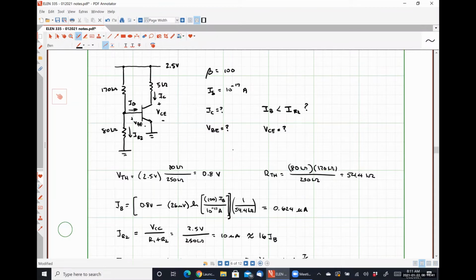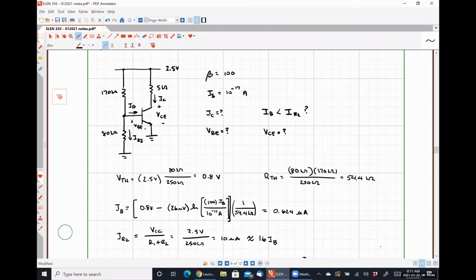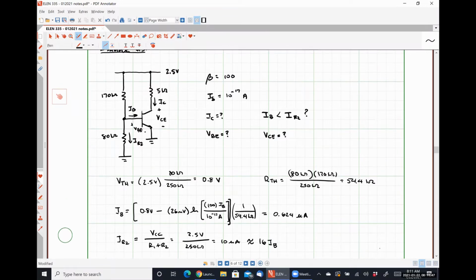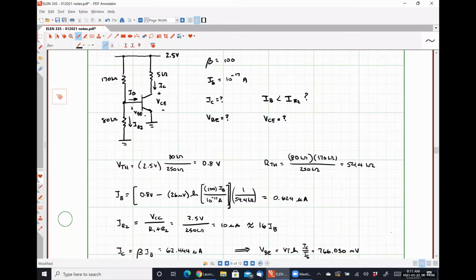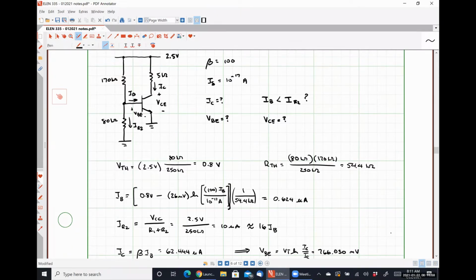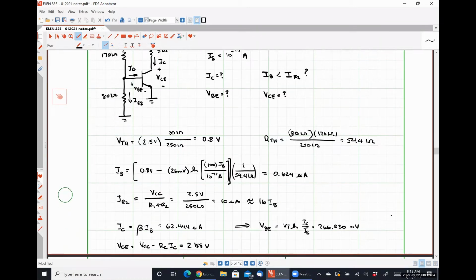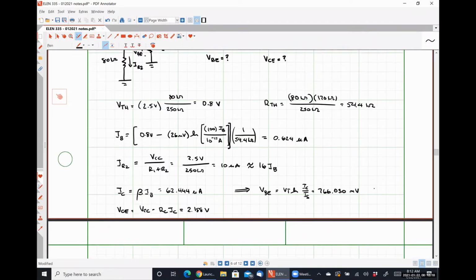So I'm calculating it by dividing simply the power supply voltage divided by the sum of those resistors. But I want to be very clear here that that is not an accurate representation of what the actual current is, right? The actual current through that resistor would be VBE divided by 80 kiloohms. But we're just trying to see, roughly speaking, how this compares to our other model where we neglect the current to see what percentage of that current it would be. So, any other questions on applying this particular biasing scheme?